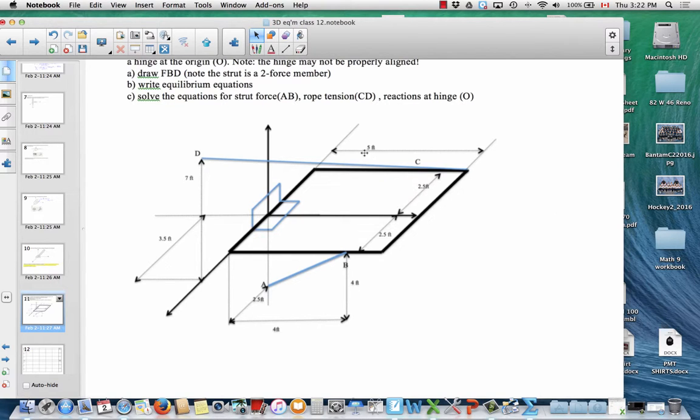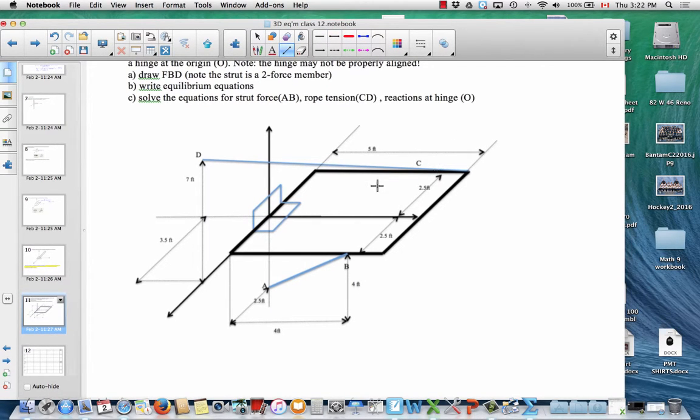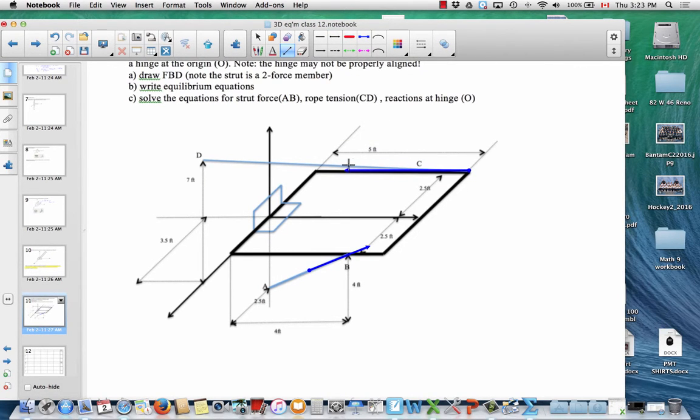So our first job is to do the force diagram, and then we will find everything in Cartesian, and then we'll apply the conditions for equilibrium. So this door is going to be pushing down on the strut, so there'll be a strut force along the AB axis. Okay, so other forces. There's the tension force here. So given that the door has weight, the string's going to be pulling up from C towards D. It's kind of not cooperating very well there. Okay, let's leave it like that.